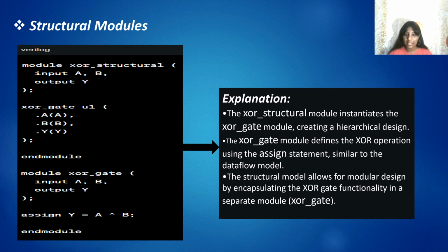instantiates the XOR gate module, creating a hierarchical design. The XOR gate module defines the XOR operation using the assign statement, similar to the data flow model. The structural model allows for modular design by encapsulating the XOR gate functionality in a separate module, XOR gate.